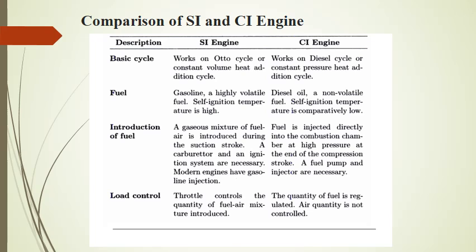In the case of the CI engine, what is happening? Air is basically compressed during the compression stroke and fuel is injected directly into the combustion chamber at high pressure at the end of the compression stroke theoretically. So for this function, a fuel pump and injector are necessary.